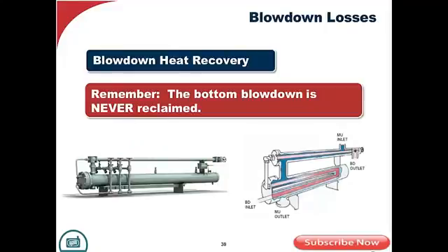Now, blowdown losses was also a part of the criteria of in-service efficiency. If we've got continuous blowdown with a boiler, I'm trying to control the TDS level at 1,500, or maybe it's a bit less, or maybe a bit higher.